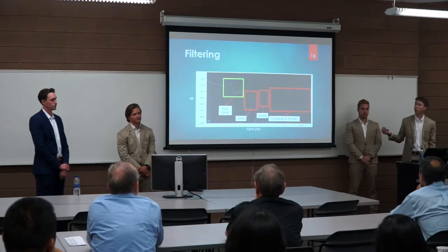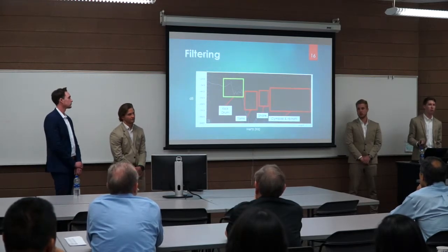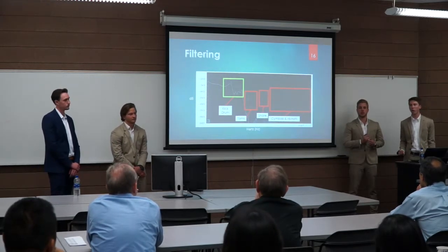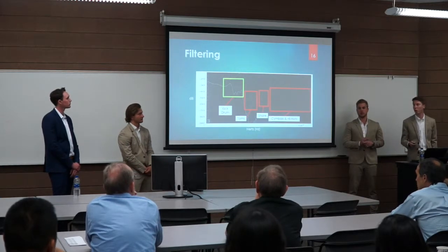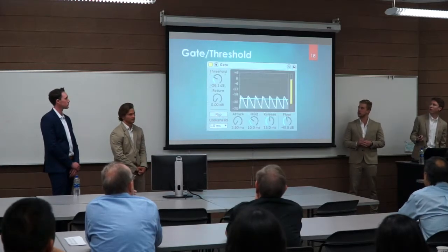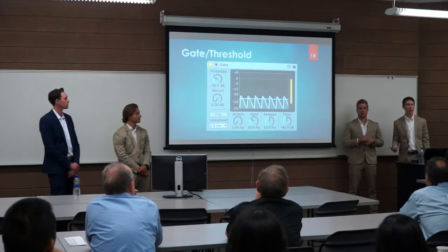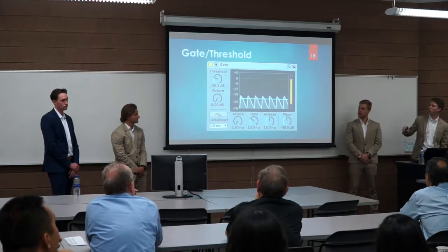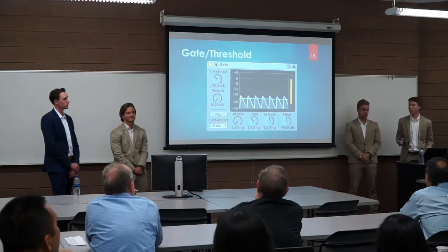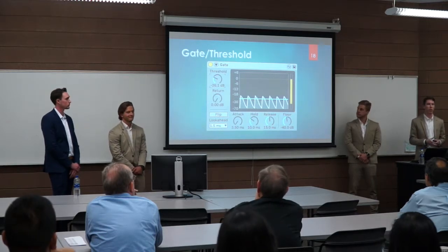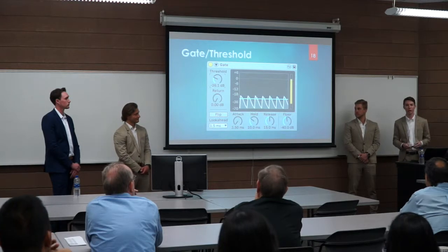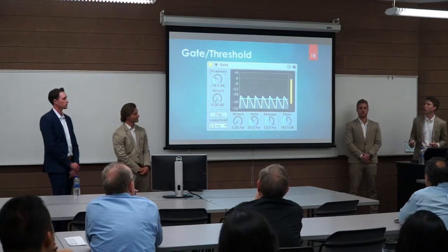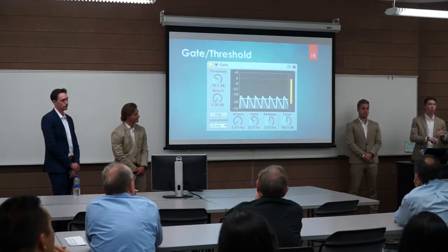As you can see, the kick drum is still loud, while the other drums are no longer present in the audio file, and now we're able to go through our gate process. I designed this gate based off of an Ableton program that I use, and the two main important things here are the threshold and our return value. So we wanted to set our return to be 0, so it's the same dB as what's coming in. And then our threshold determines what level goes above and what level goes below.